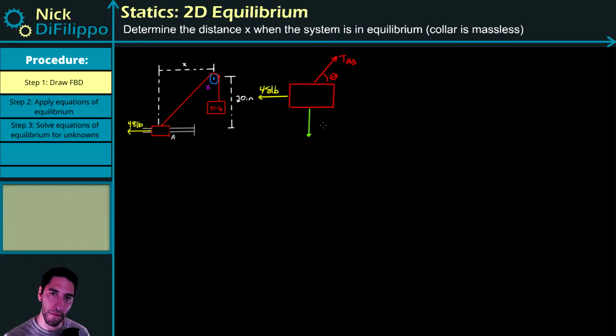So in order for equilibrium, this tension is going to have some positive force that goes up. The normal force is going to have to be exactly the same, and it's going to have to point downward. So we'll call this my normal force. If you didn't see that and you had assumed that the normal force pointed upward, that's okay. At the end of the problem, all that means is your normal force will be negative. So you'll have a negative number, which means it actually points downward.